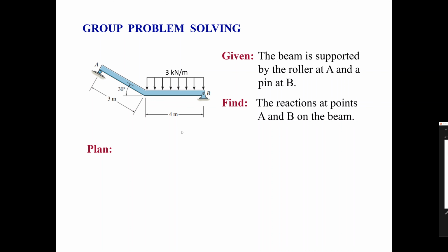Okay. Now, looking at the support over here and the support over here, which connect this beam to the outside world, these are the external forces acting at these places. So we're going to have an external force acting here at the middle, 12 kilonewtons. Then this is a roller support. So there's no reactive moment, and there's no reaction along this line here.